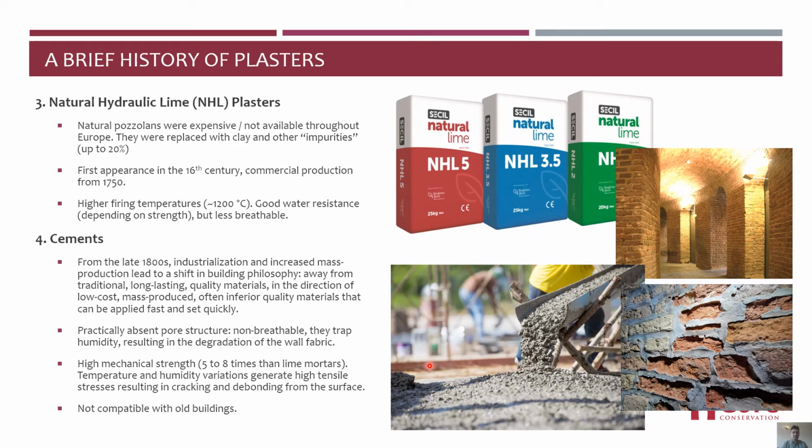They are very, very strong. The mechanical strength is about 5 to 8 times stronger than lime mortars. So temperature and humidity variations generate high tensile stresses, just stresses inside the material, resulting in the cracking and debonding of the cement from the surfaces. And in these cases, the softer building material, the soft bricks, always suffers because it ruptures much more easily. As a result, they are not compatible with all buildings and the use is not recommended.